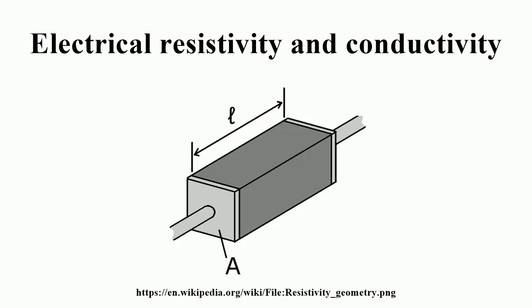Wood is widely regarded as an extremely good insulator, but its resistivity is sensitively dependent on moisture content, with damp wood being a factor of at least 10^10 worse insulator than oven-dry. In any case, a sufficiently high voltage, such as that in lightning strikes or some high-tension power lines, can lead to insulation breakdown and electrocution risk even with apparently dry wood.